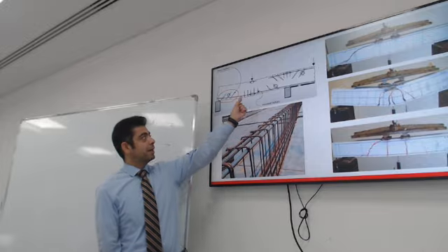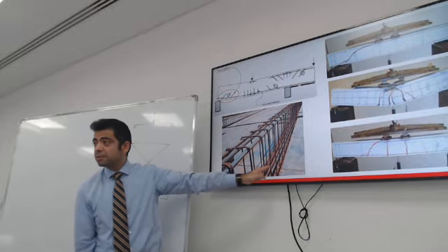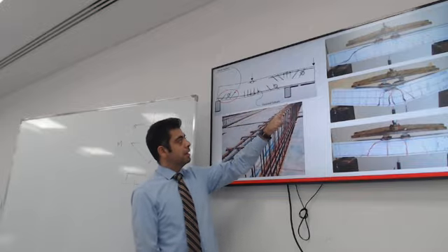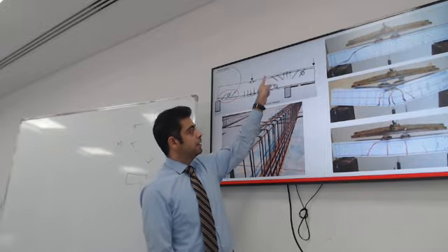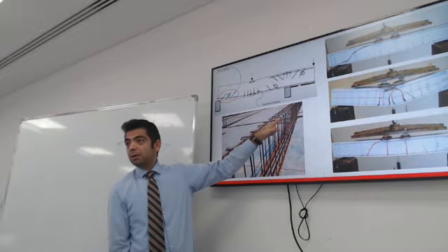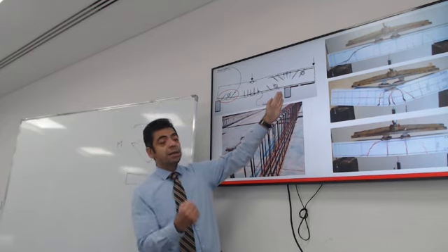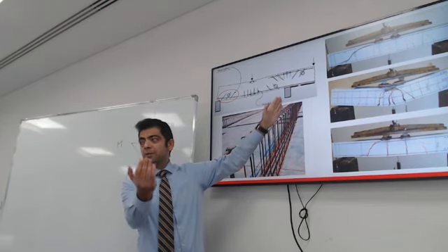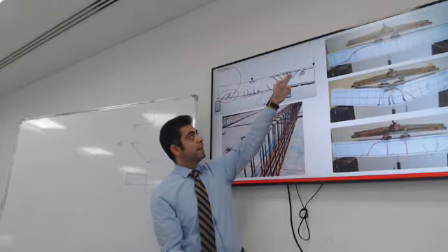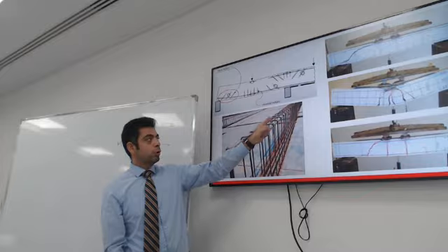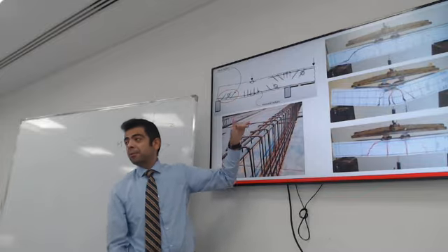The black line is the bottom bars in the beam. The top black line is the top rebar, and they are useful and significant at the continuous support. A continuous support will have a negative bending at the top, and therefore you need reinforcement bars at the top and at the bottom.